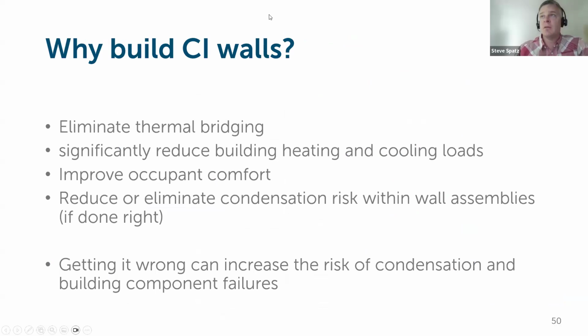Let's see if there's any questions. Is a 1 millimeter drainage plane gap large enough for the size of a water molecule? Yeah, that capillary break is really what is necessary. The bigger the gap, the more drying potential you would have for exterior driven moisture, water that would get into the assembly behind it.